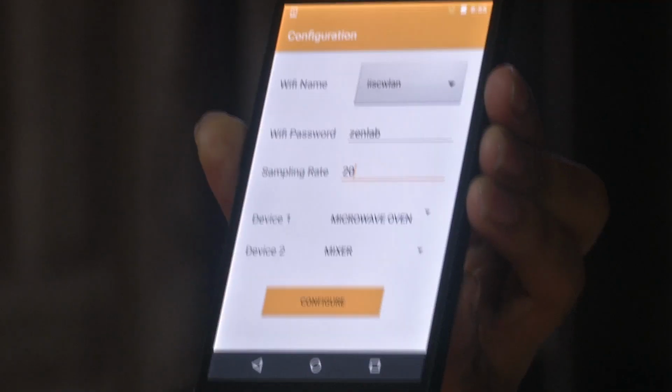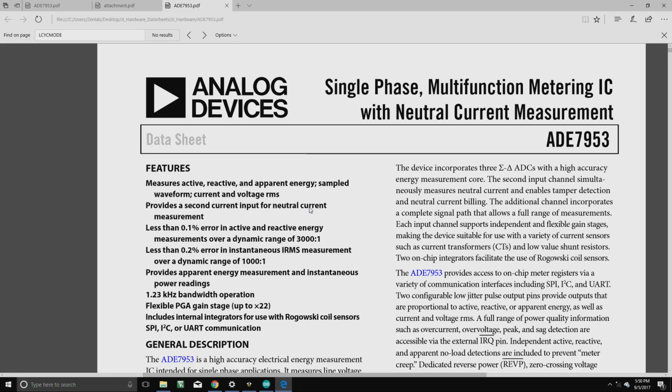Okay. So, let us go back and look at how we should go about working with this Joule Jotter in order to get our IRMS, VRMS, output power, power factor, and so on and so forth. The heart of the whole Joule Jotter indeed is this chip called ADE 7953.